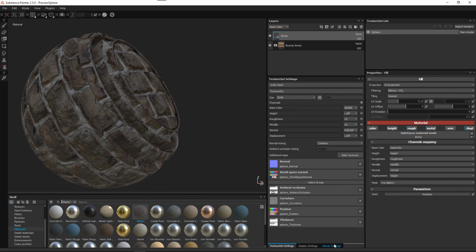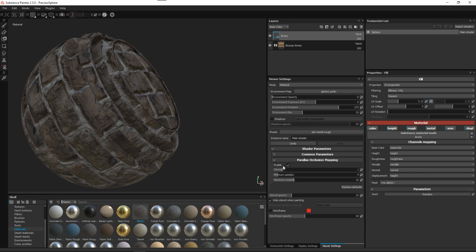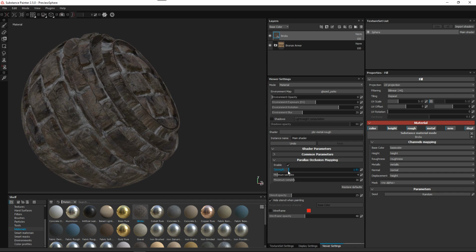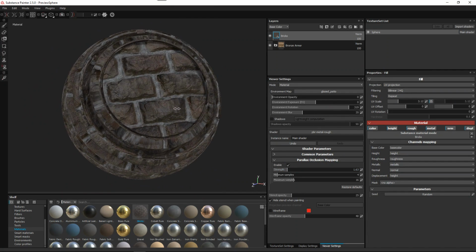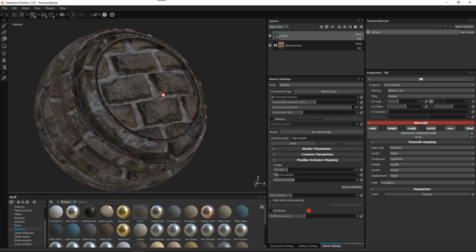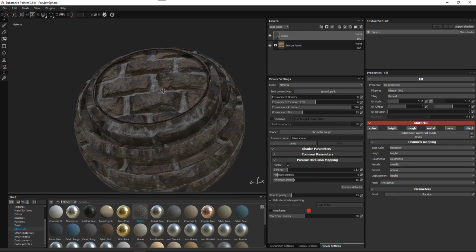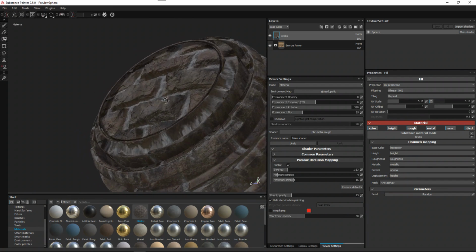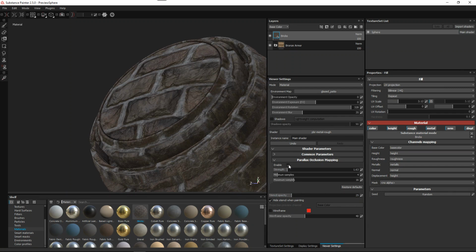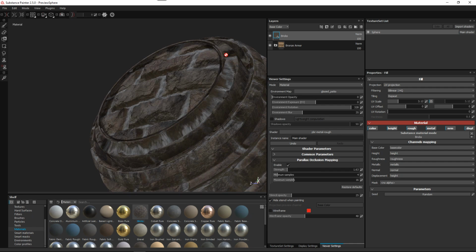Let's go back over to my viewer settings, and I've got this enabled. Let's start to increase my strength here. And now you can start to see where I'm getting this parallax occluding effect. Again, if we zoom in and focus on this area, you can see what this looks like with it off. But here it is, off and enabled. Now I've really overcranked it, so I'm getting some distortion here, but I just wanted to drive home